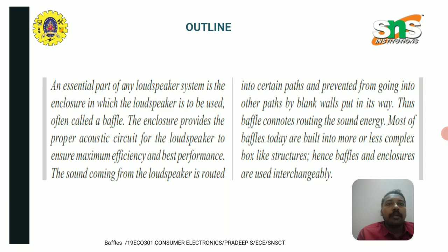Outline of this topic. An essential part of any loudspeaker system is the enclosure in which the loudspeaker is to be used, often called a baffle. Most baffles today are built into more or less complex box-like structures. Hence, baffles and enclosures are used interchangeably. The sound coming from the loudspeaker is routed into certain paths and prevented from going into other paths by blank walls put in its way. Thus, baffles control routing of the sound energy.